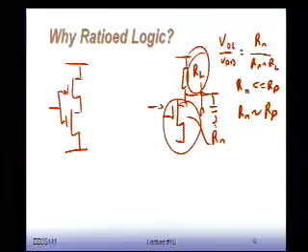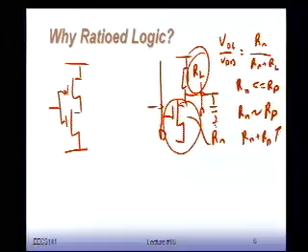This logic family, or this class of logic families, will see, when the output is low, the current to this chain of resistors is not going to be zero. It will have current flowing. This gate has static power consumption. Right? If you don't do anything, there's still going to be current flowing. So again, for that, I would like to have Rn plus Rp as large as possible.